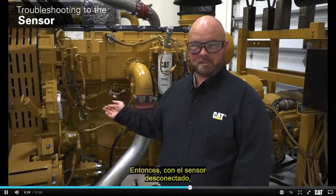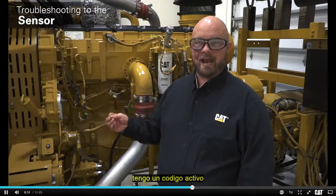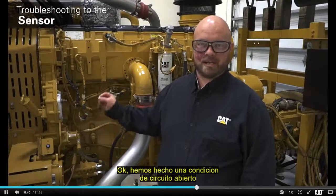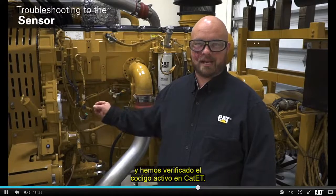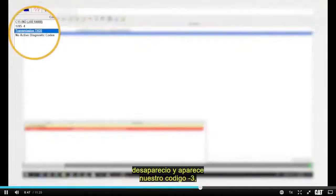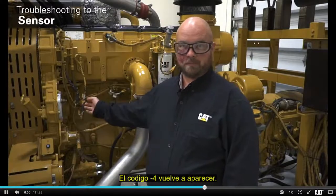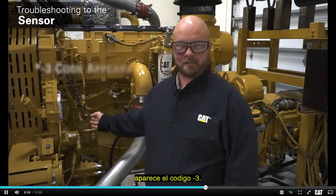So with the sensor disconnected, what I would expect to happen is CAD-ET would tell me that I have an active -3 code, voltage above normal. That's what the ECM should be reporting at this point. Okay, so we've made our open circuit condition out at the end of the harness, and we've checked the active code on CAD-ET. If at this point our -4 code disappeared and our -3 code appears, what does that tell us? Well, when we connected the sensor back up, if our -4 code comes back up again, and when we disconnect it, the -3 code disappears.